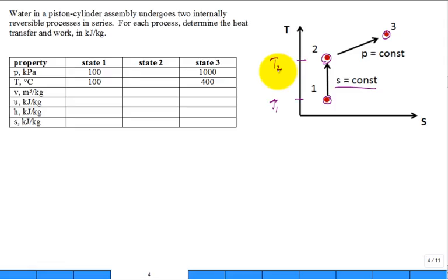This is where I'm going to stretch your imagination a little bit, or see if you've started to develop some expertise in thermodynamics by solving a lot of problems and having some insight into the problem. How could that be realized? How could you take a system and somehow not change its entropy, but change its temperature? Compress it adiabatically and reversibly. If you compress it, you're putting work in, energy in. It's going to be realized by an increase in internal energy, increase in temperature. It's going to get hot. And if you did it without any heat transfer, that means no entropy transfer with that heat. So the entropy stays the same.